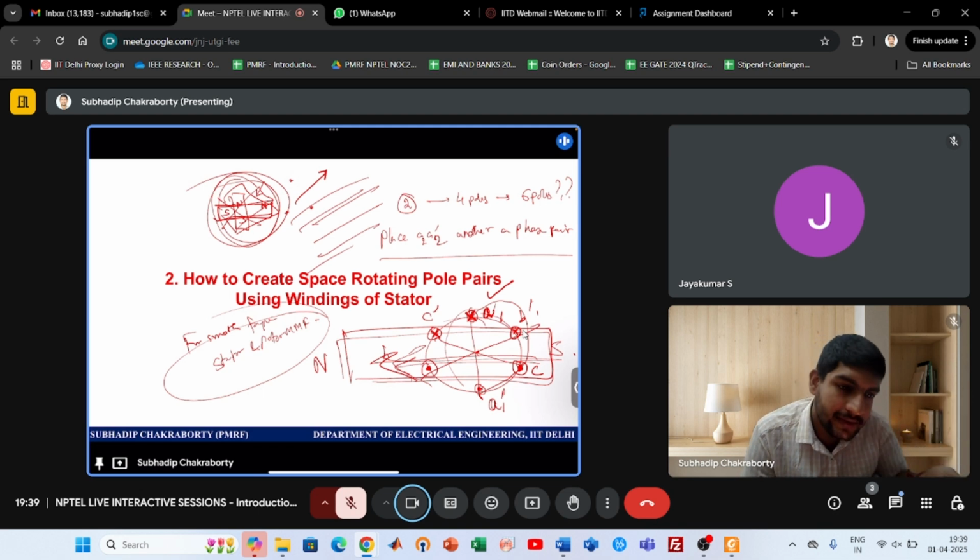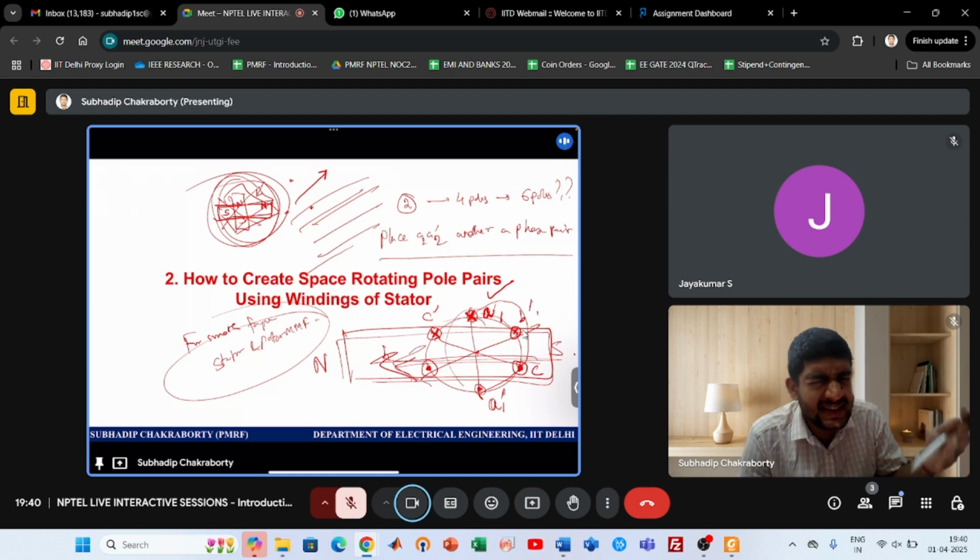After you increase the number of pole pairs by putting in multiple phase A coils in the stator, that group of slots in the rotor reduced. Now you can keep on doing this until you reach that constraint, when you are equaling it with the number of rotor slots, because above that the rotor cannot adjust itself to make that number of pole pairs. So the number of rotor slots is the constraint to create that number of poles, right?